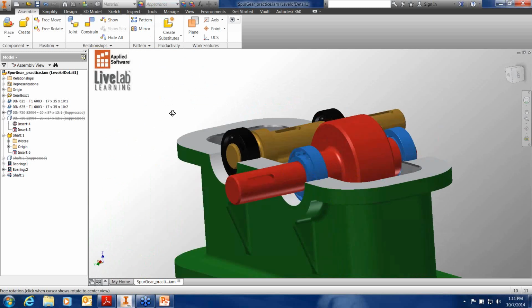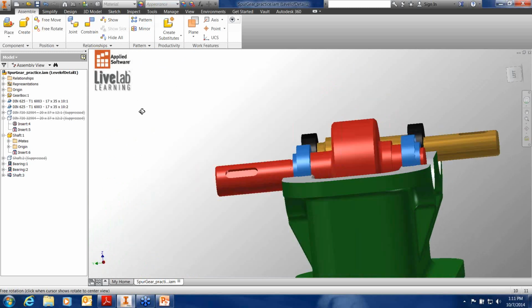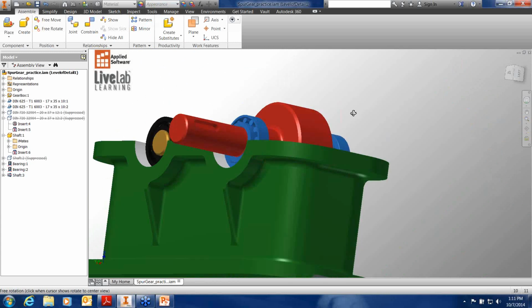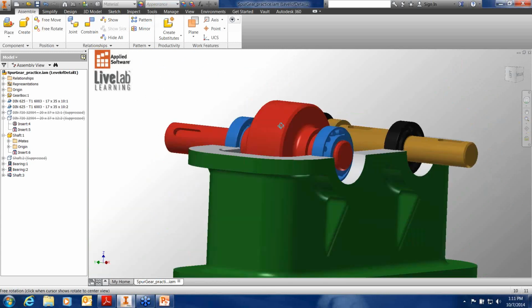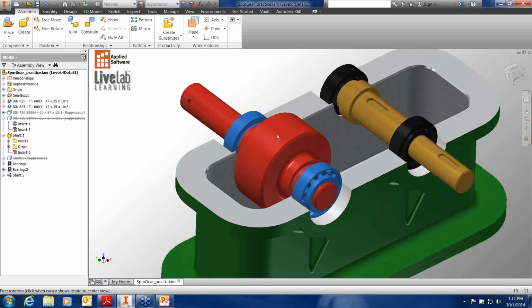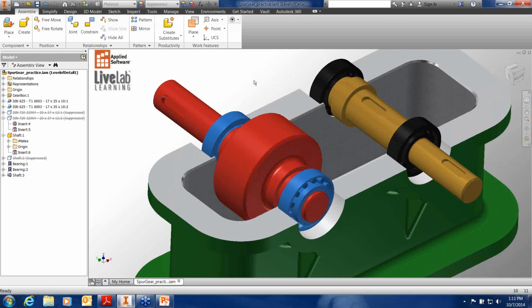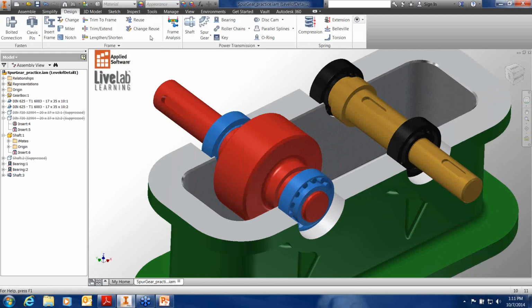All right, so at this point now we've used the shaft generator to actually generate our shaft. And now we're going to look at the gear, creating the gears based off of the shafts. Now, when we come back to our Design Accelerator, we've got the spur gears, the worm gears, and the bevel gears. And this we're going to real quickly look at the spur gears.